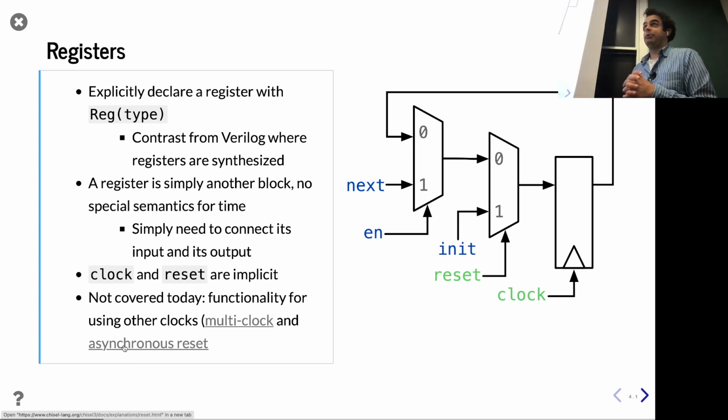Another way to make this more clear is that Chisel, as an intentional language choice, rather than optimizing for all these special cases, is assuming modern era Verilog design. In modern era Verilog design, latches are used almost never. Everything is synthesized, and active low is pretty rare.